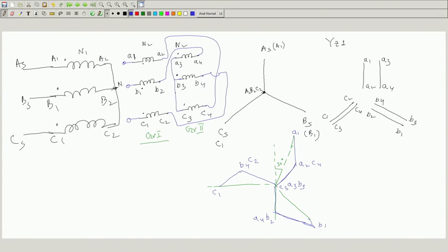Only thing is between the neutral, secondary neutral, that is N, to one of the lines, if you start your journey from neutral, you will come across 2 coils belonging to 2 different phases, that is A phase and B phase in this case, if you start N, from N traverse A3 A4, then traverse B2 B1 and get your supply B, this is supply A, load supply side, this is C. So, two coils are in series.